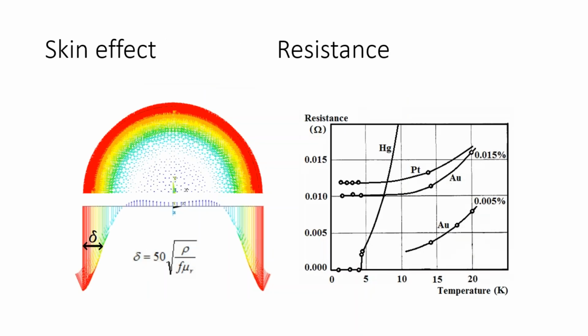The AC current is most frequently used for resistance heating in the industry, and this leads to a non-uniform current distribution in the workpiece due to the skin effect. So as we all know, the incident current produces the changing magnetic field. This field produces eddy currents in the material, and these eddy currents are oriented in such a way that they partially cancel the incident current, and mostly on the interior of the conductor. So therefore, most of the current will be in the skin zone or in the exterior zone of the conductor.